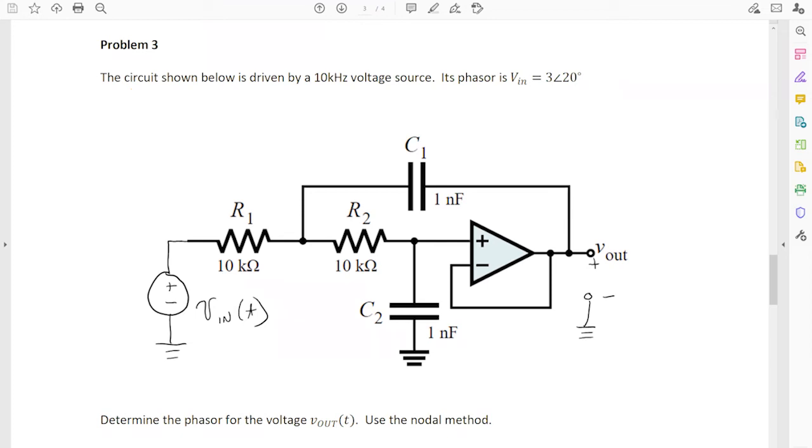So ground, more generally, we talk about references. A circuit has to have a reference point, my 0 voltage point. So in that sense, I can have different reference points, possibly. That is not a good idea typically. Sometimes it happens. Let me just wrap on that: you'll never have a circuit with different grounds in here, just to be clear.